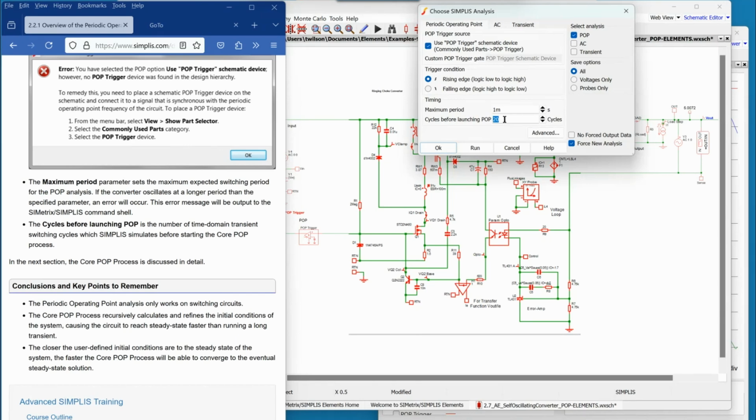Right. So if you would usually have a 20 millisecond soft start sequence first, for instance, you would like to squeeze it to the smallest you can before starting the POP in that case? Well, in general, you don't want to use POP to power through a soft start.